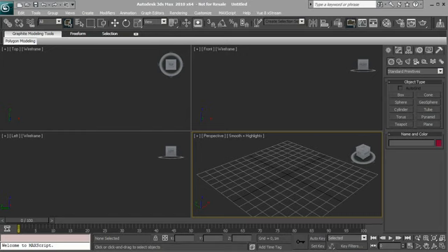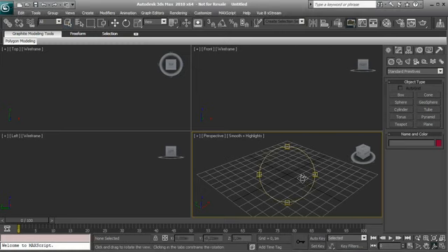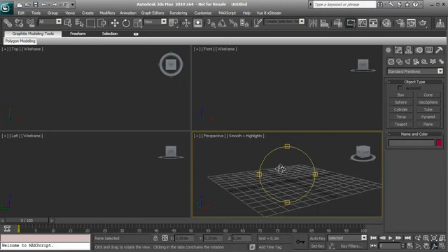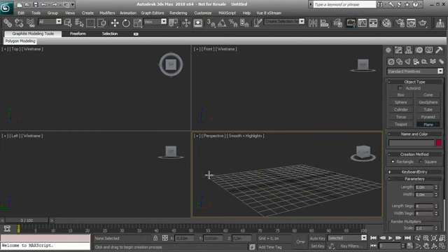This time we'll talk about toon shading inside 3ds Max, and we'll talk about the toon shader and the contour shader for Mental Ray. So there are two ways to create toon rendering inside Max: one with the scanline renderer and the second one with Mental Ray. The first one is the toon shading based on the scanline renderer, and we'll start to work on this one.